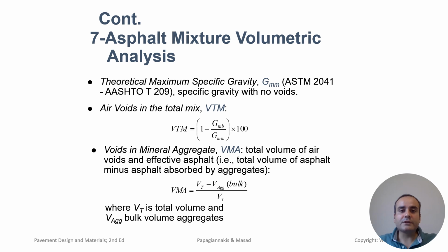If air voids are too high, the pavement can become permeable, allowing water to infiltrate, which can lead to moisture damage and freeze-thaw damage in cold climates. Excessive air voids also weaken the structure, leading to early cracking.